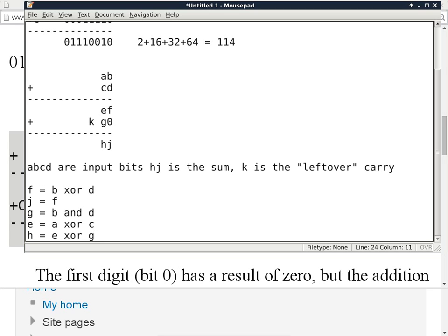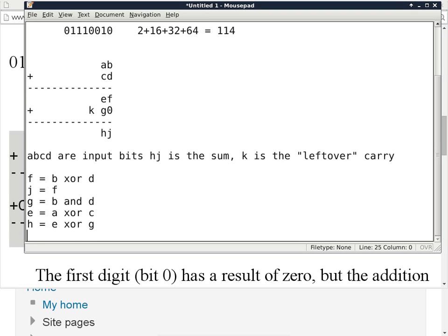What about K? K is the first time we see a carry bit that can have two possible contributors. Because A plus C can contribute a carry of 1 to K. E plus G can also have a carry of 1 and contribute that to K. So it's going to be the and of, and the or? Okay, let's figure out the components first. I will basically give you the two components, and then we'll figure out what has to go here to combine the two components.